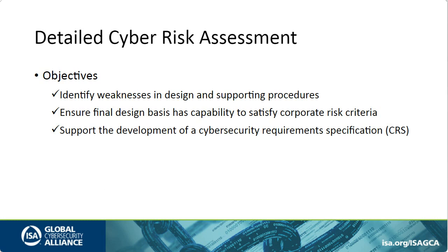Okay, objective of the detailed, assuming we need to do one, we want to identify weaknesses in the design and the supporting procedures. We want to ensure the final design basis has the capability to satisfy corporate risk criteria, and we want it to support the development of that cybersecurity requirements specification at the tail end of the work process.